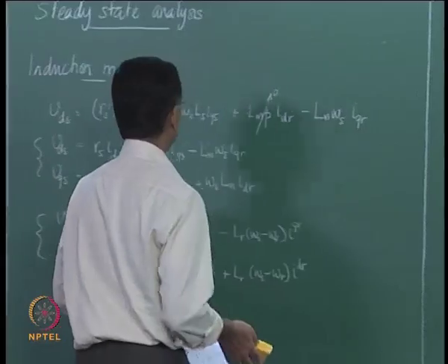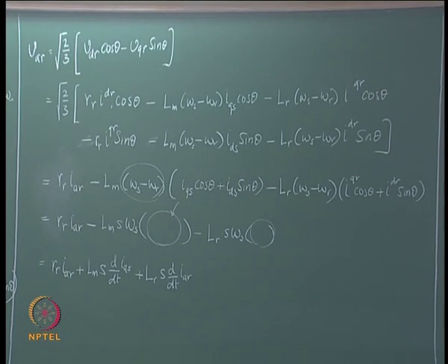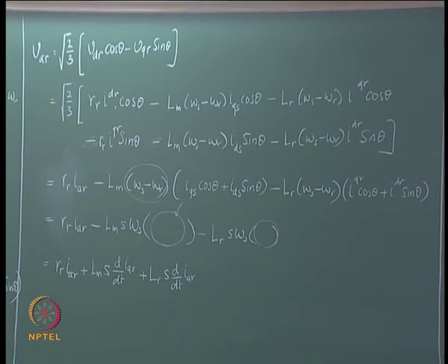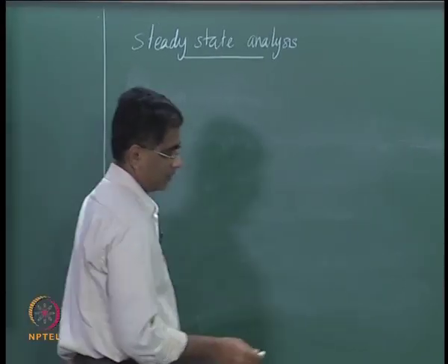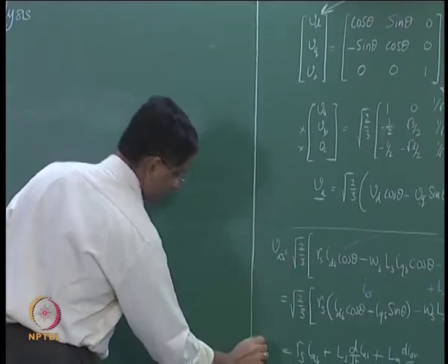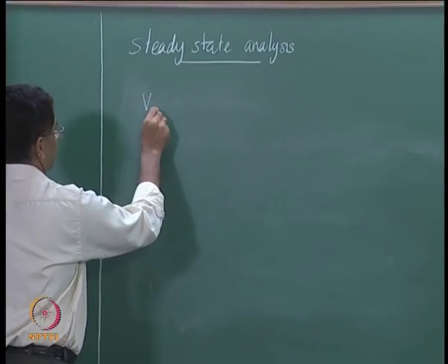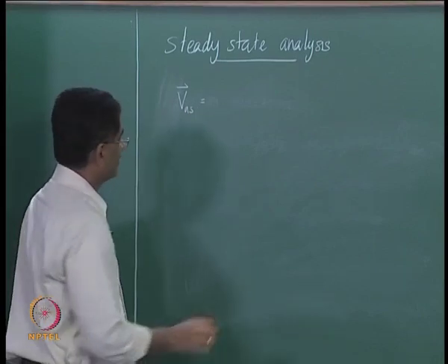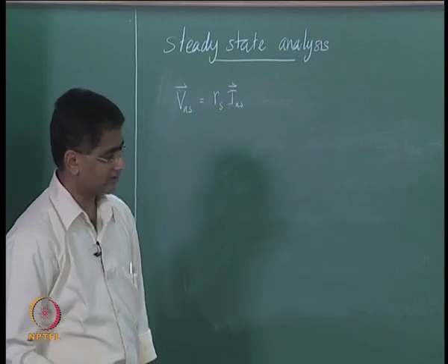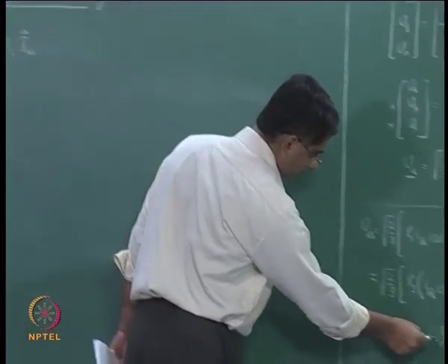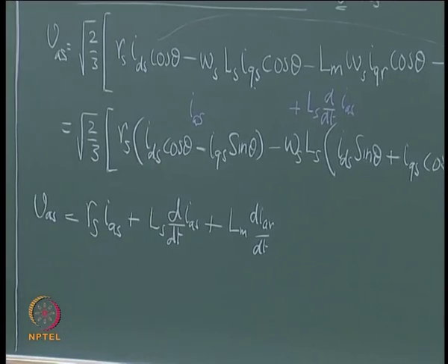So, what we will now do is convert to the phasor notation to make it easier to handle. So, the first equation is the equation for the stator voltage VAS. So, VAS as a phasor is then equal to RS into IAS, where I is a phasor, and now you want to represent this one Ls d by dt of IAS.